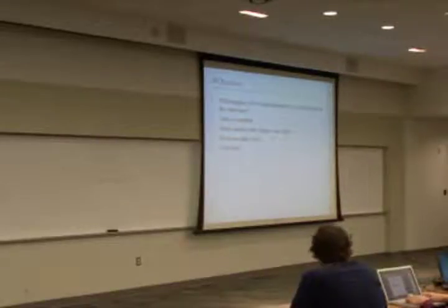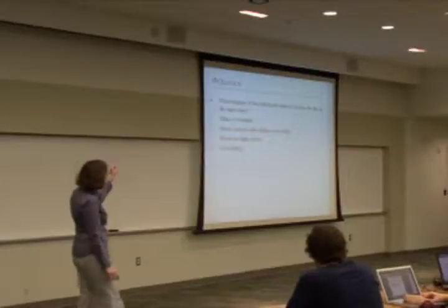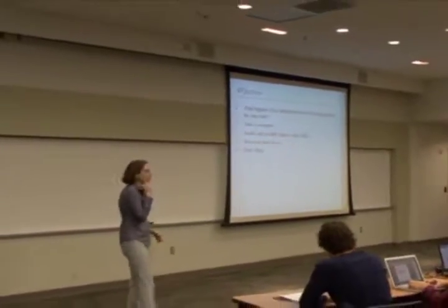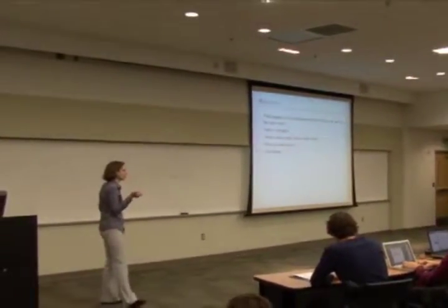So if I now put 2 volts on my bus, A, data will definitely be corrupted. B, you will have possible smoke or fire. If the processor doesn't shut down, it will burn. So pretty much all 4 answers are correct, and they will happen in this order. If that happens for a very short period of time, it may not burn.